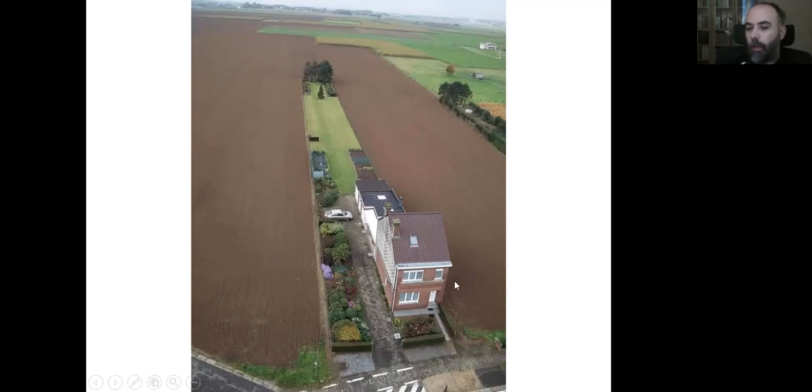We need to indicate everything that we see, and the scale can be determined according to the size of this area. If it's too big, we can draw the site plan in 1/500 or 1/1000, or if there are very important things that we need to show in the near surrounding or in the far surrounding, again, we can change the scale into 1/500, 1/1000, 1/2000, something like that.